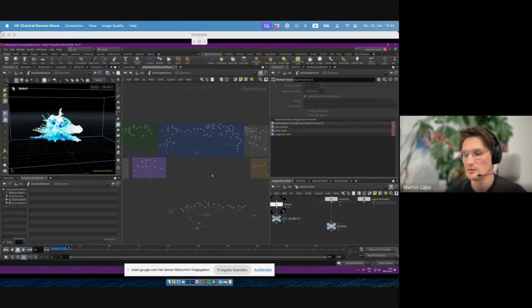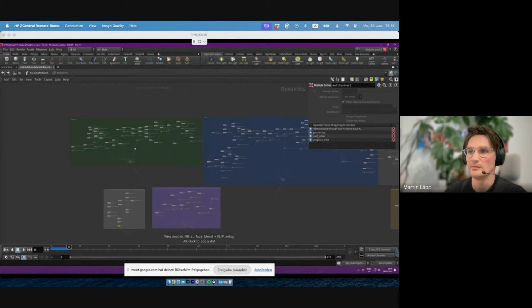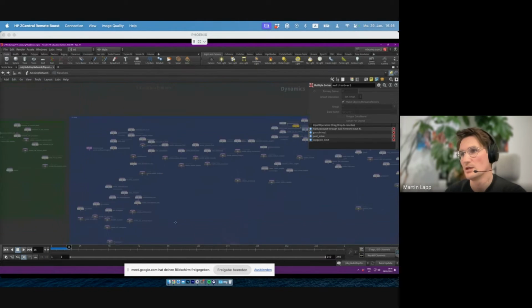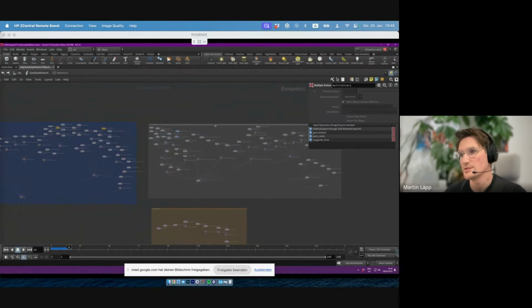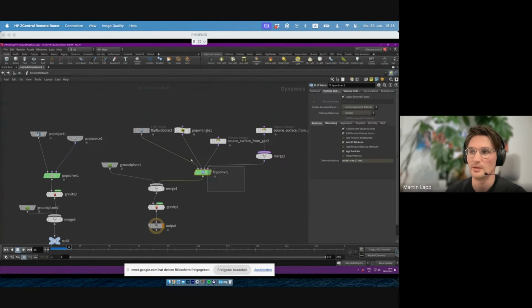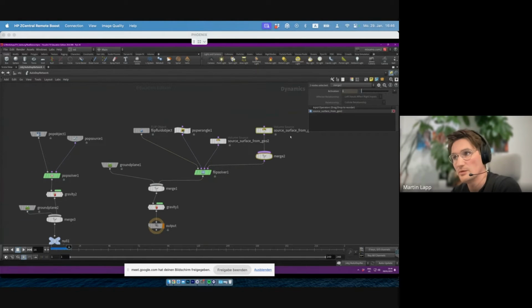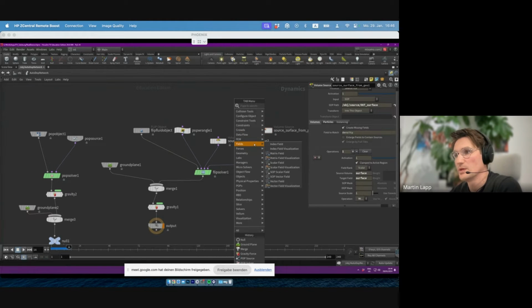And if you dive inside, you can see all this, right? There is a bunch of microsolvers in here. There is project non-divergent simulations. There's a lot of stuff happening here that is all wrapped up in this flip solver. And if you really want to go down to the micro level and change stuff down there, you can do this either by creating different forces, because there is a lot of stuff that you can add here as well.